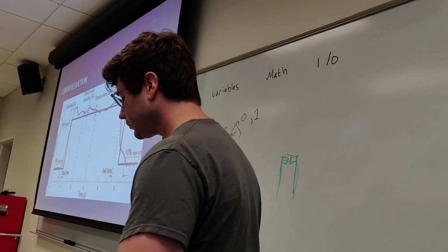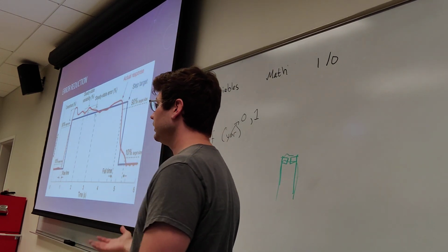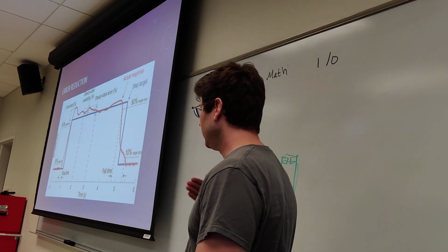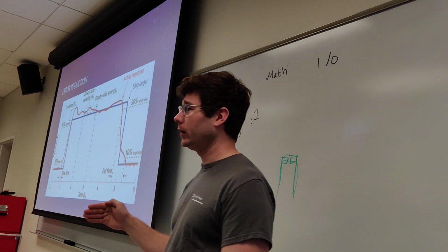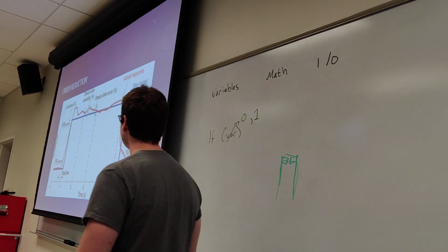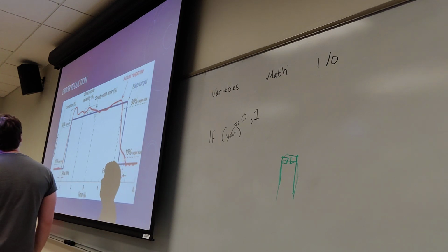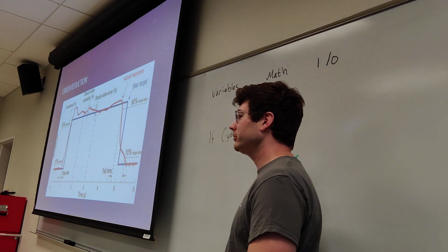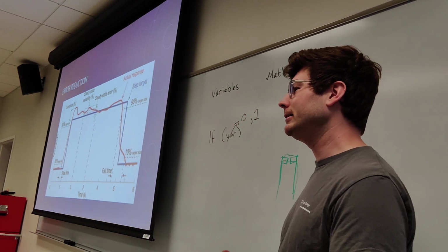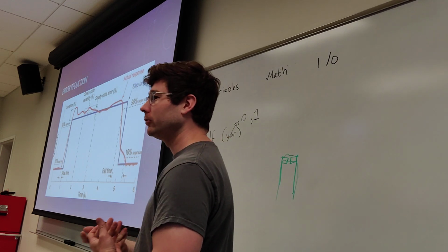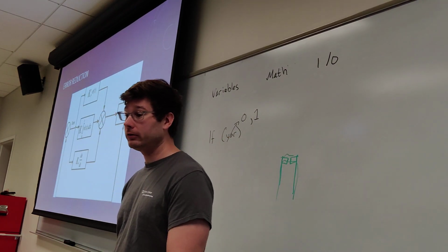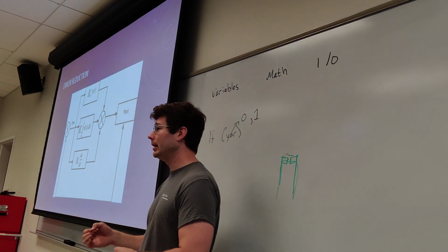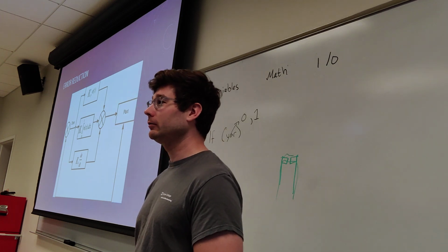So what we do is we try to respond to that error. If we see that the car is slowing down because we hit a hill, or because we hit some wind, we can increase the accelerator, respond, and restore the state close to our set point. What I'm describing here, the name of the game is error reduction. Controlling a process is driving the error to zero, if you've never heard that term before. Mathematically, a lot of these algorithms literally are ways to reduce some number to zero. And that number is how far off of our mark we are.